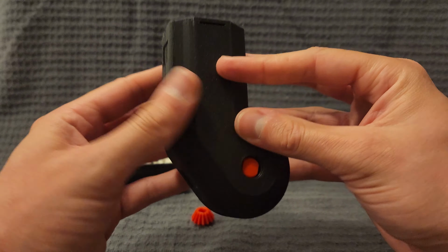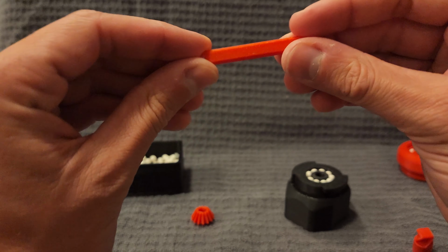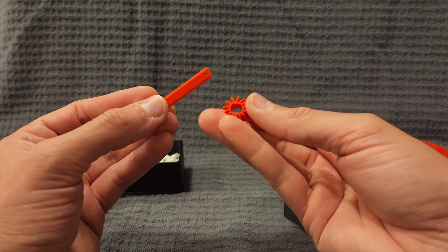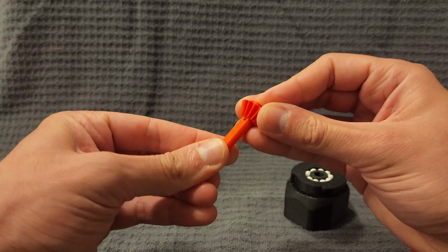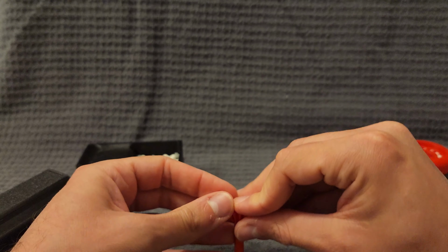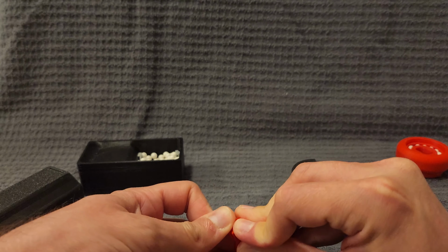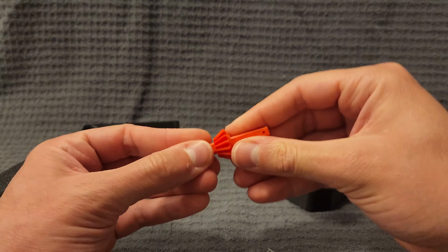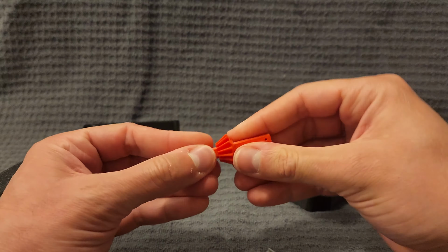Now we will finish the assembly of the top case. So start with the top shaft. The shaft has a hole on one end as well as a step on the other, and make sure you insert the pinion gear in this direction. After pressing in the gear, it's going to rest against the step at the very end of that shaft for its location. And then you can insert that in the top case. Should go in pretty easily. And then just press in the propeller connector on the other end.